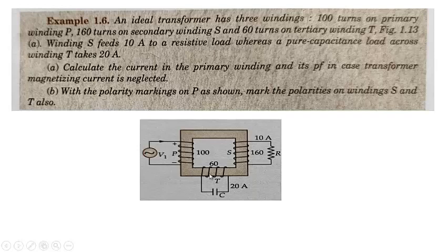Similarly, for this case, it has to produce the flux upward in the anti-clockwise direction. So when we put the fingers in the right direction and see the direction of our fingers, it will be like this. That means current will be leaving at this terminal, and this will be positive, and this will be negative. So in this way we are done with the polarity markings, and I hope you have understood this.